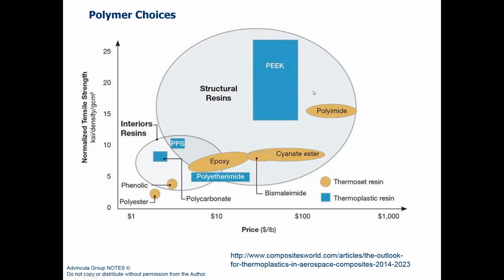On the other hand, thermoplastics is just one subset of polymers. Polymers can constitute thermoplastics, elastomers, and thermosets. Thermosets are essentially cross-linking material systems such as epoxy, cyanate ester, polyimide, or phenolic-based resins. On the other hand, high-performance polymers like PEEK or even PPS are essentially thermoplastics with a high melting point and can be crystalline or amorphous.